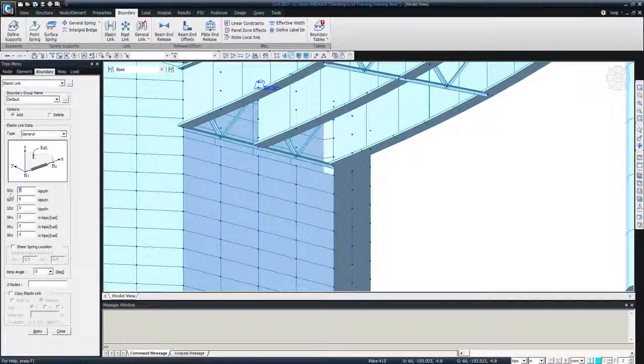You always see that when we have the lowercase x, y, and z, it means that those are for the local coordinate system. Whenever they are in capital letters, definitely they are in the global coordinate system. So now I have the local coordinate system, and imagine that we're going to create one link right here. So dx always is along the direction of the element. So this vertical direction right here will be local x direction for the bearings.